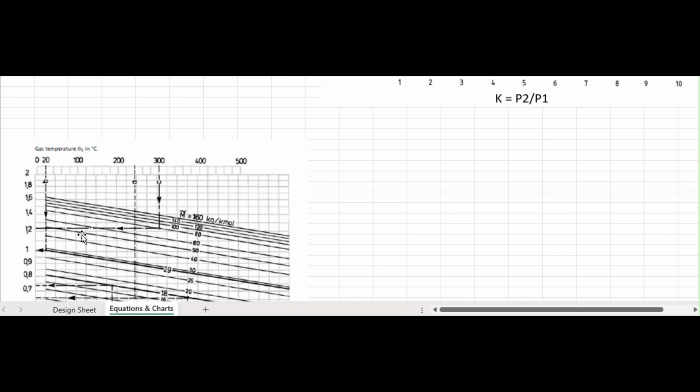So you have the 40 with the 50, this 40 coming here, intersect with the 50 at around 1.22, okay? Now, you could calculate your equivalent water suction flow, which is your off-gas flow multiplied with your equivalent flow factor, divided by your suction factor, okay?